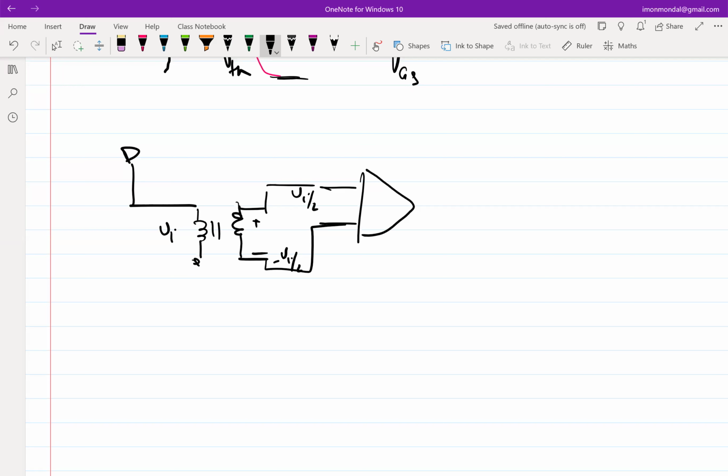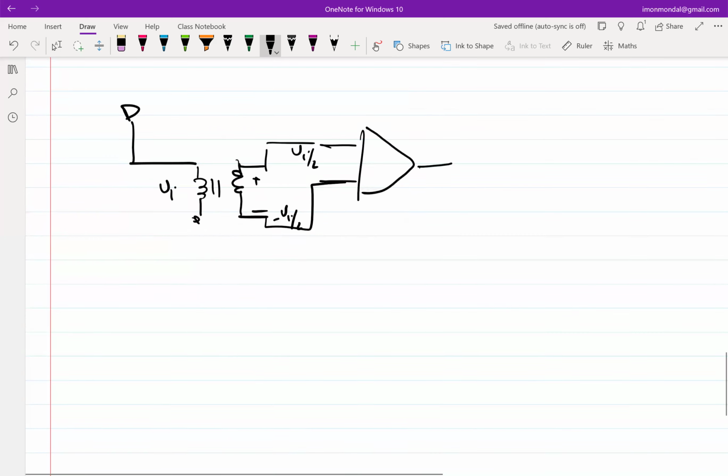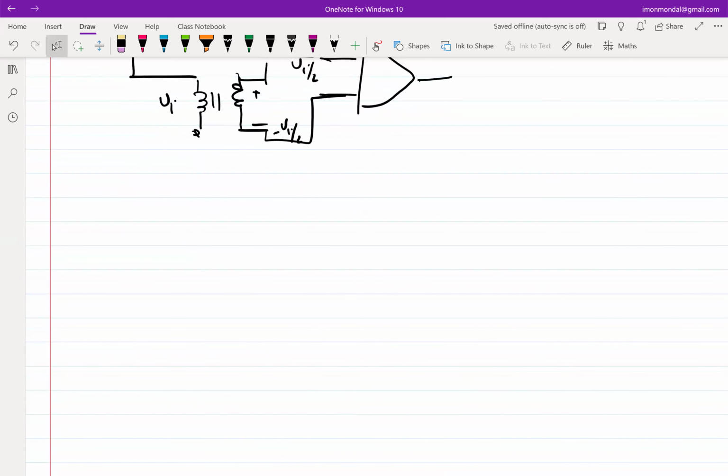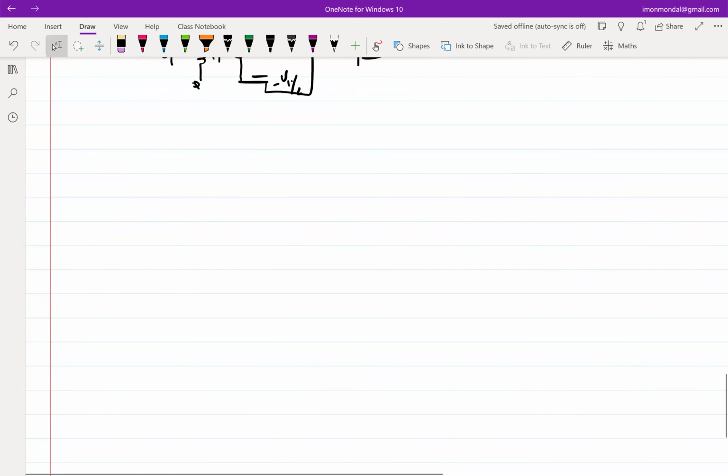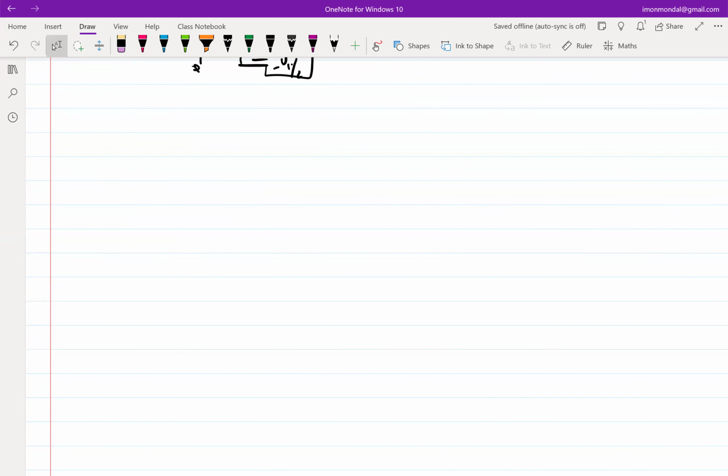At times, these baluns are difficult to make on chip, especially at lower gigahertz frequencies, since inductors are bulky. So they are kept off chip also, right? So that's not an issue. So now that you have a differential signal, I'll not talk about that part I was introducing. I'll talk about it in the mixer. So let's now shift focus to an LNA design, right?